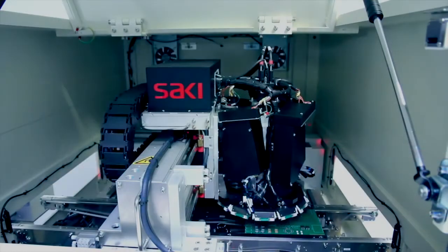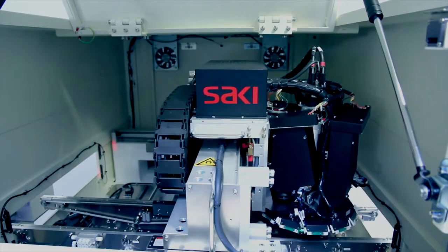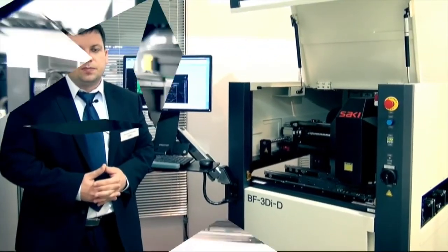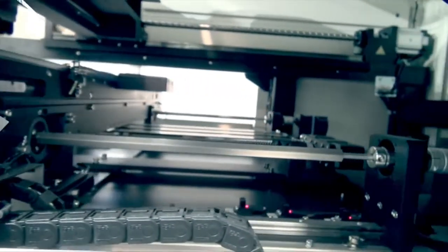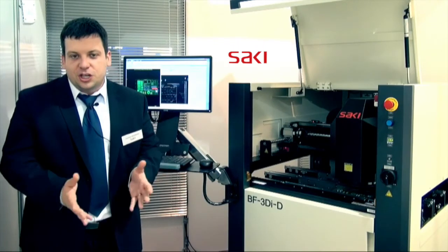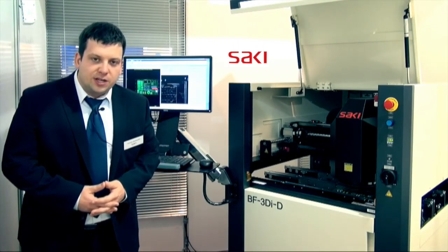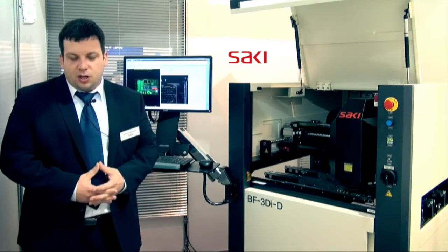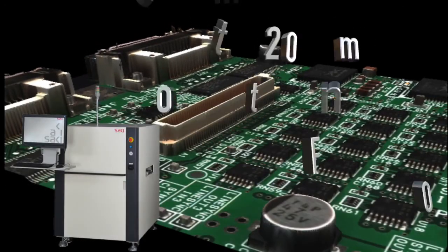size version. The gantry is driven by a ball screw, despite the fact that the previous generation was driven by linear motors. And the programmable projectors were optimized in a way that we changed the projection angle in order to eliminate the secondary reflections, and the homogeneity was improved. Therefore, the height reconstruction is much more reliable compared to the current generation.